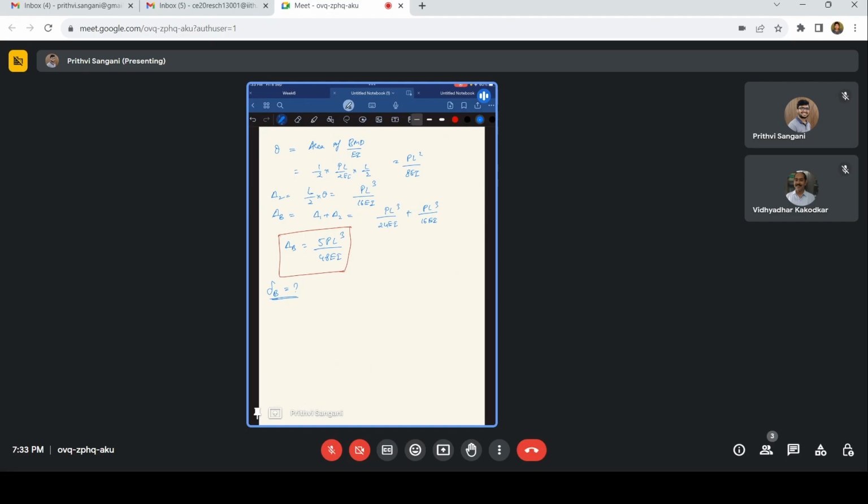So this is how we usually work on it. So I hope now it is clear how we are making use of the compatibility equations here. So the compatibility is again nothing but we try to break the indeterminate beam into two determinate structures, and we'll find the common point there. We'll try to find out the displacement, and then we'll try to equate the displacement. Right now we are using this; the same problem can be solved by another means also, right?